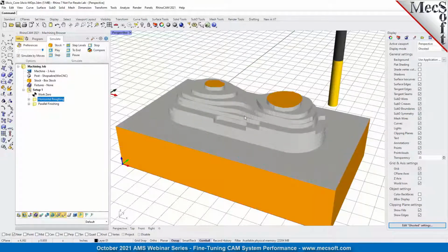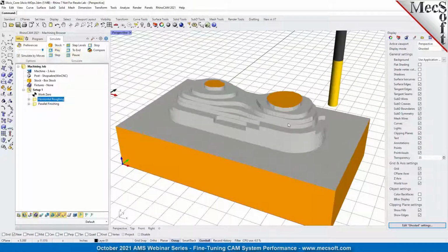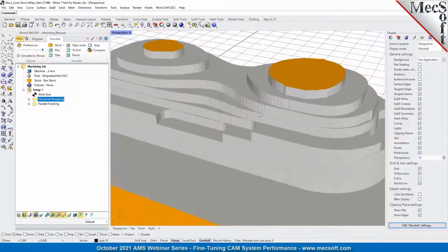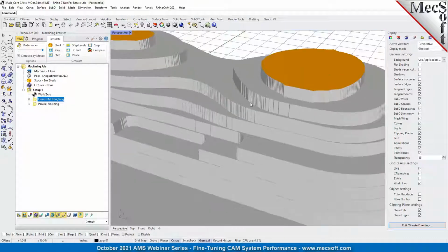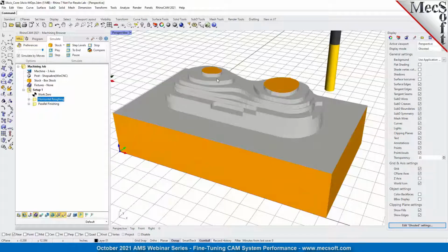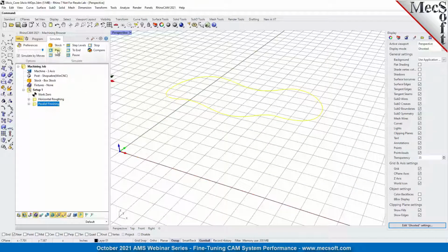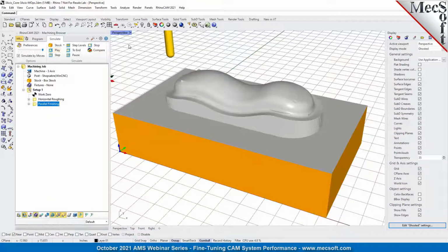So this is how fast it went through the roughing operation. It took like 2-3 seconds. Now, Joe, you mentioned that there are some artifacts in the Z-axis. If you zoom in and you see these vertical artifacts, that is not in your toolpath. That is the voxels. You're basically looking at the voxels displayed there. So don't worry, it's not in your actual toolpath. Let's do the parallel finishing on the voxel. It's going to whip through that pretty fast, like 2 or 3 seconds.